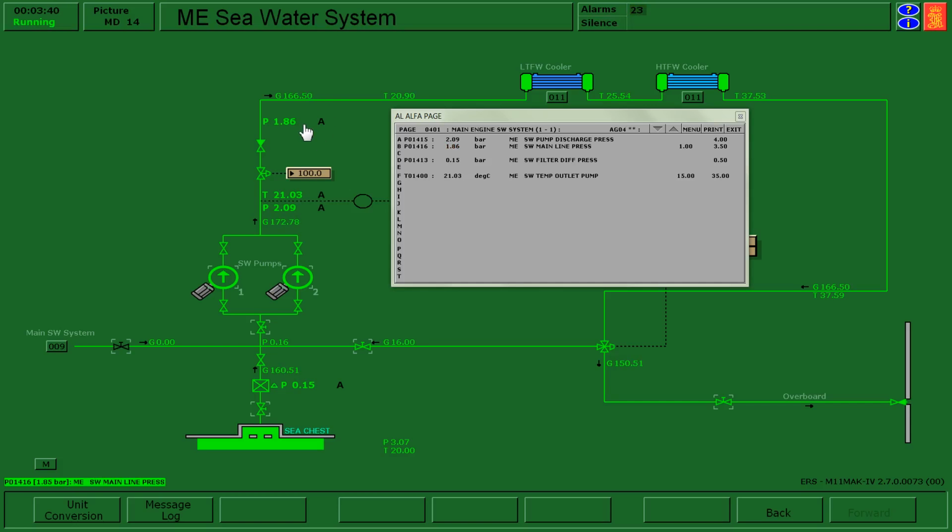There's a good reason for why you want to click on it. Number one is that maybe there's a situation where the alarm has happened and you weren't monitoring the system. Well, if it happens to solve itself, so it was some intermittent fault, what you want to know is exactly where was the alarm and what was the problem. So at some point, the pressure out of those pumps was low. And maybe you don't see it or are not part of the immediate diagnosis of that, but you want to be able to know that there was a problem at some point.